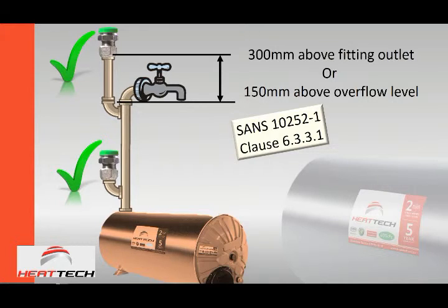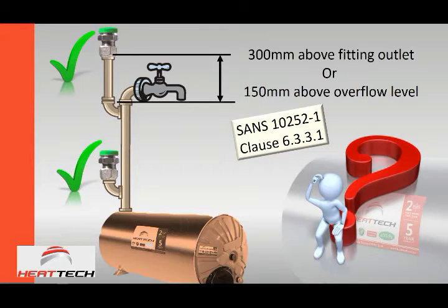The safest way is to have the vacuum breaker at the bottom as well. So you don't have to leave the vacuum breaker at the bottom, but this becomes a bit more interesting if you go through the standard. It explains various scenarios on when the vacuum breaker goes in which position. But if you are ever in doubt, put it in both positions.